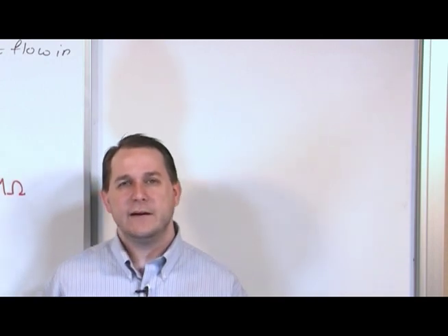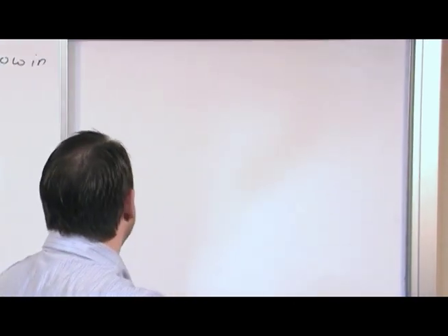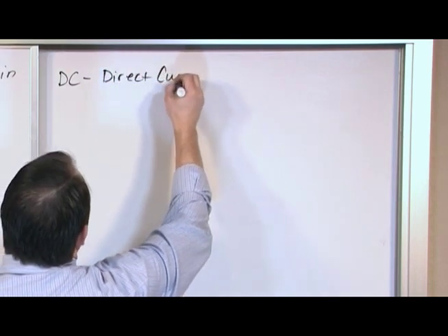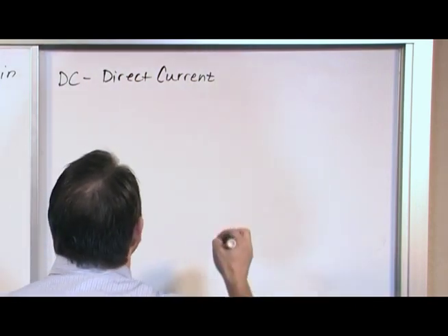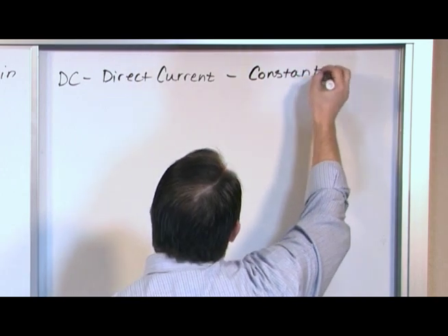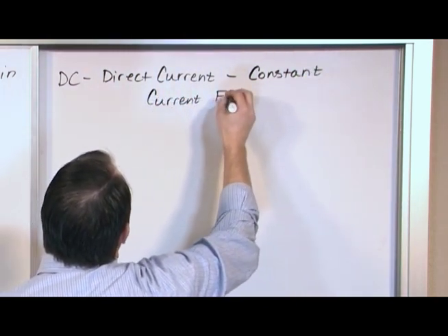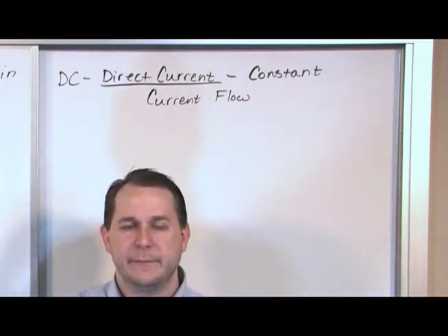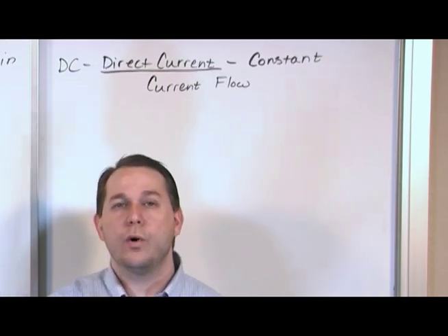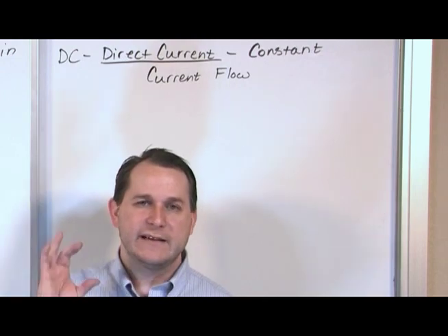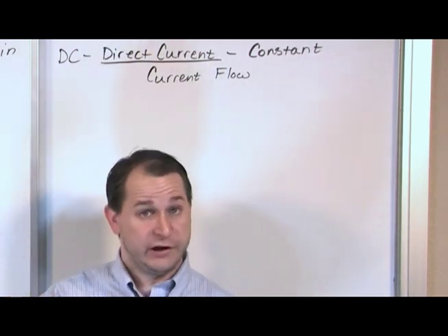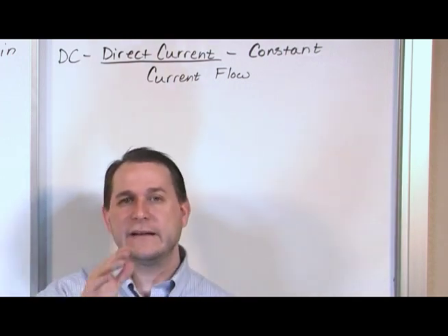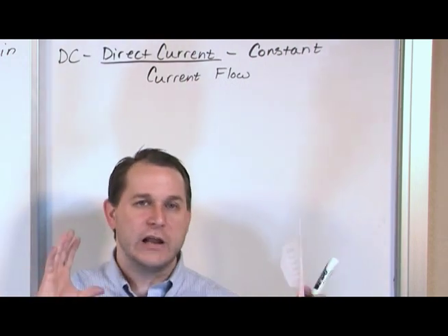First one is DC versus AC. Let's talk about that for just a second because we need to make sure you understand it. DC stands for direct current, and basically it means constant current flow. All of the batteries you've ever used in your life, the AAAs, the AAs, the 9 volts, watch batteries, anything built into a little device that we call a battery always generates a direct current. It means that when you hook it up to the circuit, it's giving you a constant voltage at the source location that's pushing current around. And because it's a constant voltage, the current that comes out is constant, never changes. Now, in reality, the battery is going to die down and get weaker and weaker, so the current does eventually bleed off. But if you take a snapshot and look at it, the current is constant.